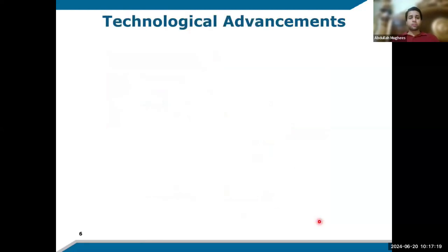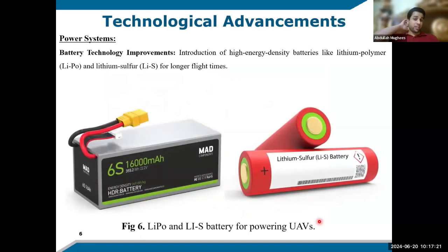Okay, moving on. So if we talk about the technological advancements, these multi-rotor systems that we mostly use nowadays, even in wings we also integrate this multi-rotor system. So we have the hybrid UAVs. We need a really high energy density source of power, because these rotating motors require a lot and a lot of current. An average size quadcopter can consume about hundreds of amperes at some instances at full payload.